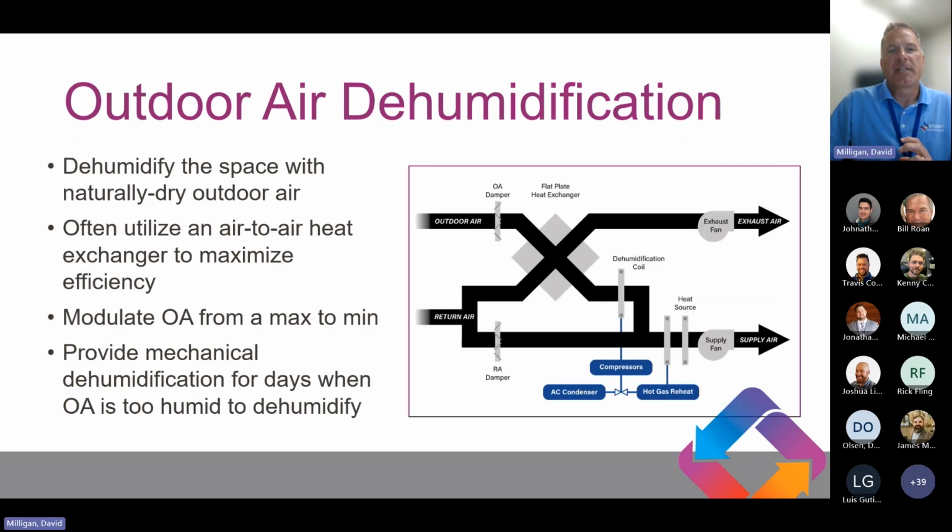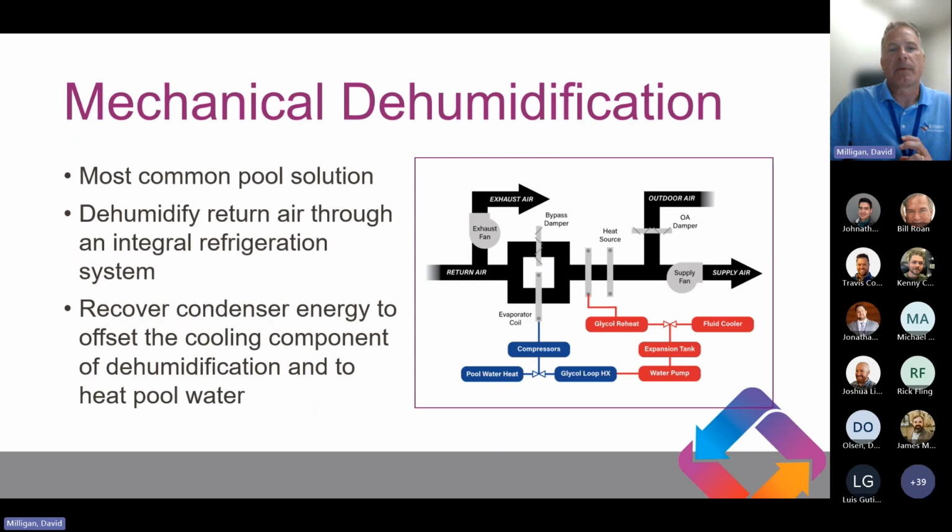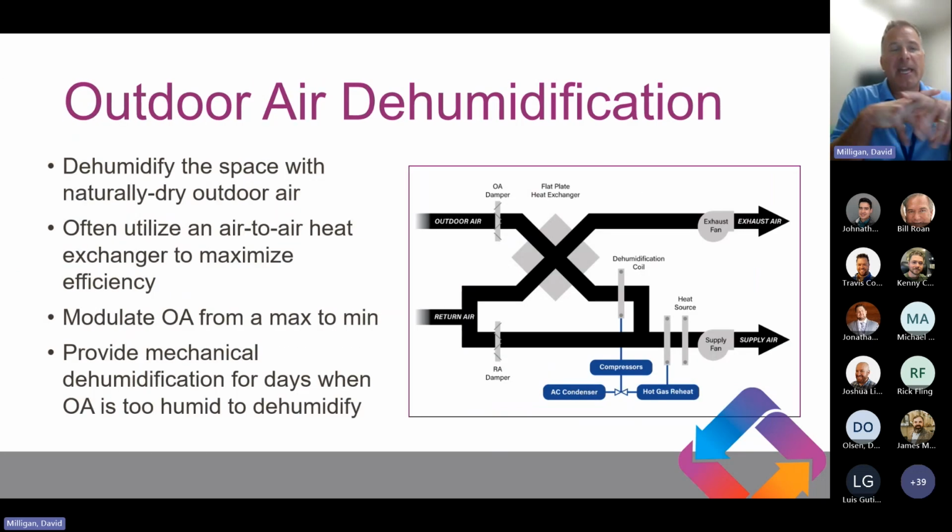The other methodology here is our outdoor air dehumidification. And like it says, we're utilizing dry outdoor air to do all the dehumidifying that's required for that pool space. And the beauty of being in the Denver area is your air is nice and dry all year round. So you really don't need to do any mechanical dehumidifying to handle most of these pool spaces. It can all be dealt with utilizing your outdoor air.